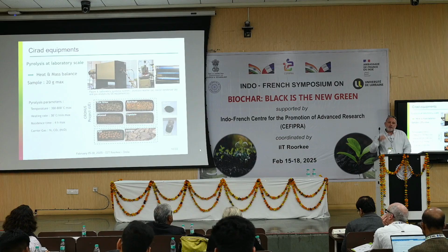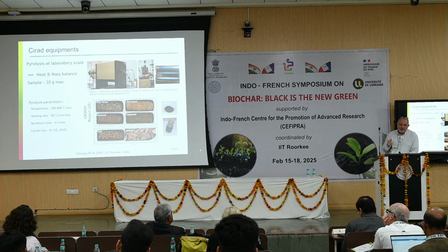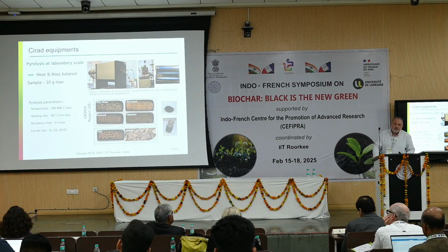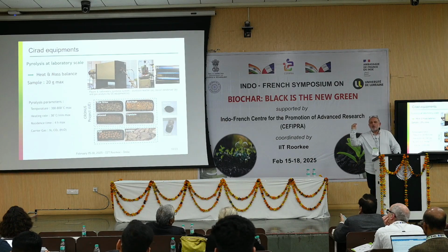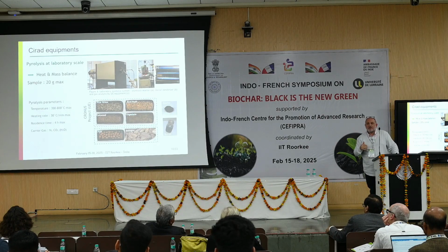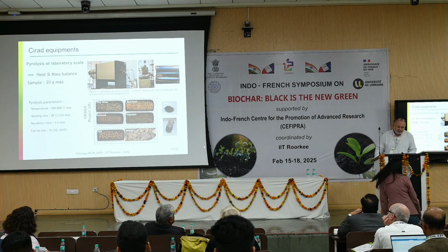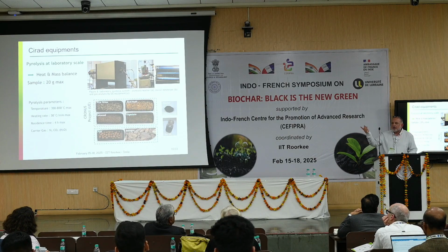The second equipment, at laboratory level: we have some reactors, but this is just one of them, where we can work with some grams of different biomass, mainly in order to determine the heat and mass balance of the process, depending on the temperature, the residence time, and also the carrier gas, nitrogen, CO2, and we are also developing the connection with steam.